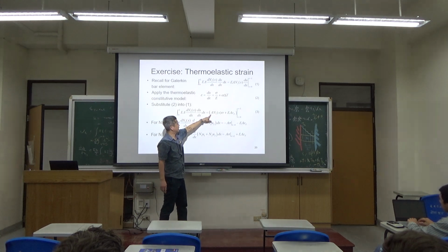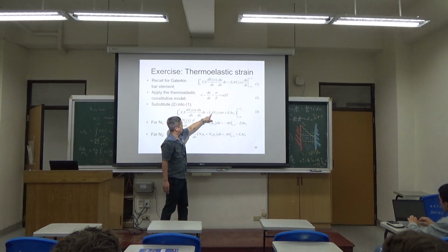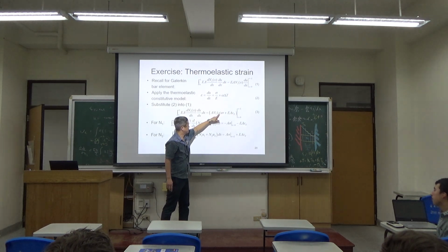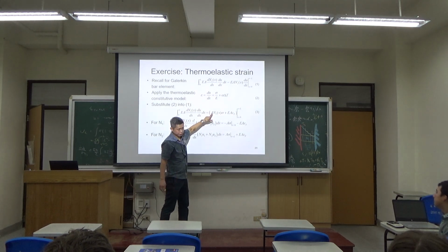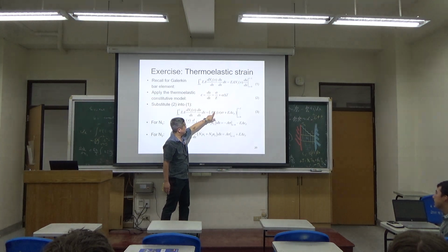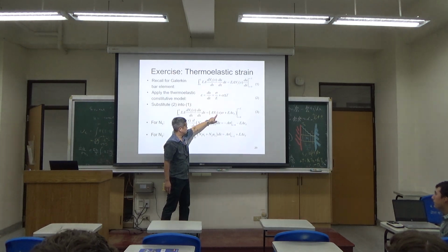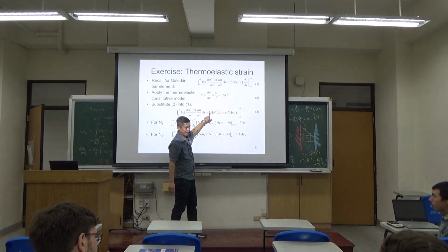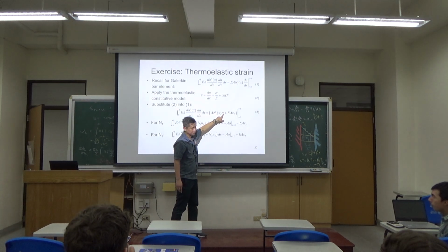Your right hand side gets area times mechanical stress times the shape function. If the shape function is 1 at x equal to 0, then your expression here is minus A sigma.